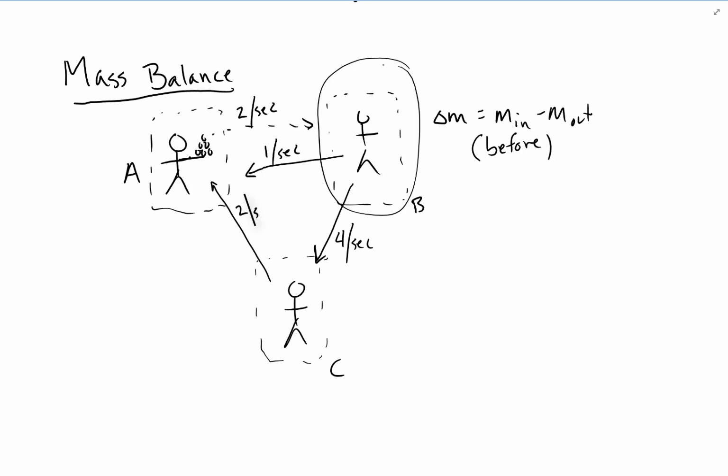Okay. To put that a little bit more mathematically, the rate of change of marbles for person B, we're going to call that m dot CV for control volume. It's the rate of change of marbles or mass inside the control volume, is equal to the sum of the rate at which marbles are coming in minus the sum of the rate at which marbles are going out. So we're going to sum this over everywhere it's going in. We're going to sum it everywhere it's going out as well. And this should be fairly obvious. If you think of rates instead of quantities, they still add the same way. If you make $10 an hour and spend $2 an hour, you make $8 an hour, right? And that's just kind of how things add up. Whether you're looking at rates or quantities, they still add in the same ways.